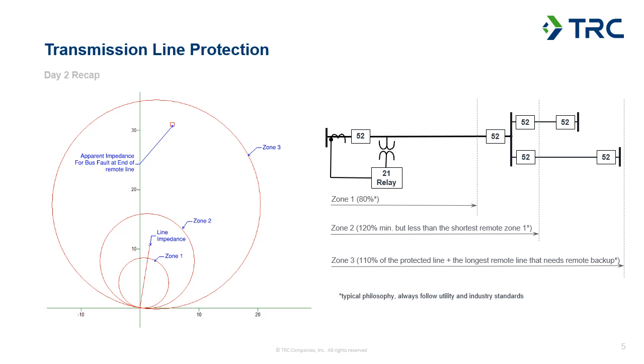We took a look at distance protection in general, how the elements operate, what we do for setting those elements, and how those elements respond and what they see for operate quantities and different electrical measurements during both normal operating modes and fault operating modes. And then we took a look at how we can use those differences in applying a reliable protection scheme that will provide coverage for the entire length of the line, as well as potentially backup protection for other parts of the system.